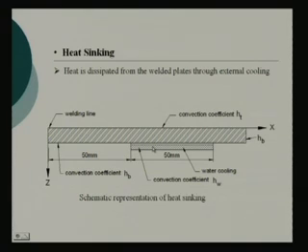So, that will take away heat and lead to lesser distortion. This is very logical. Now what is to be done? Again, like in this particular case we have studied, where 50 millimeter away from the welding zone I am putting the cooling medium. How wide have I kept the cooling medium? Another 50 millimeter. Well, it should be 50 or 100 or 500, whether this cooling is 50 millimeter or 100 millimeter away, all these are aspects which need to be seen.